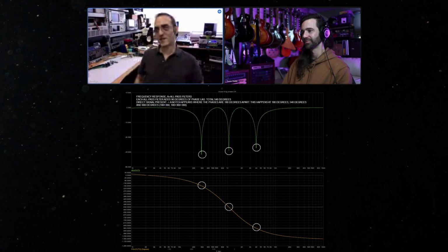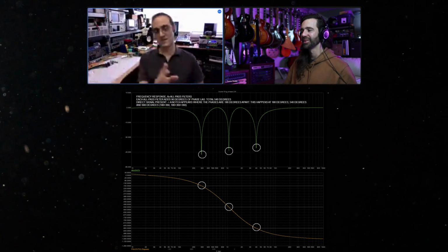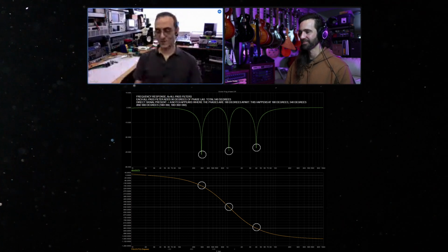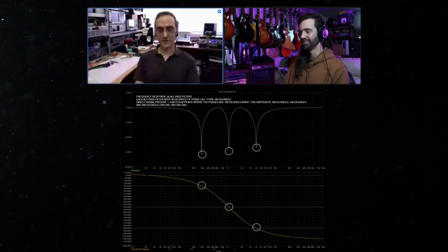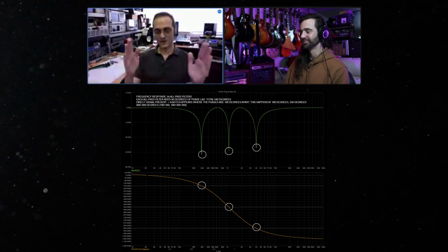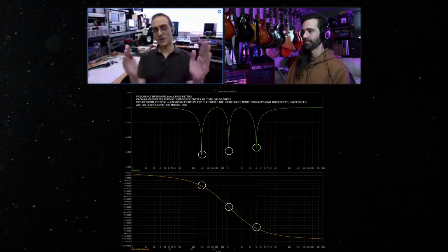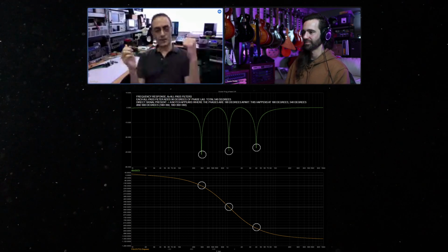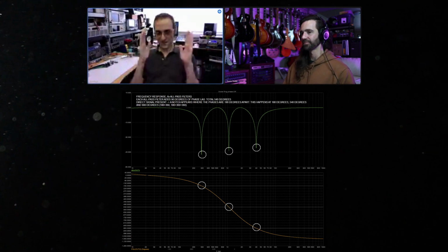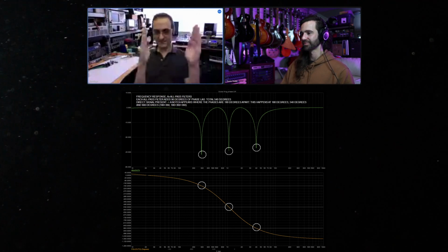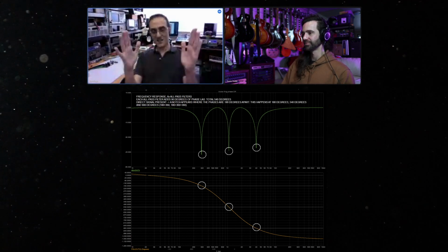I mean, in a nutshell, it's the same as a flanger, but the notches of the comb are in different places. Right. Okay. Because in the flanger, you get your signal, you delay it all the time by the same amount of delay. Your 3 milliseconds, your 7 milliseconds, whatever, is fixed. So it doesn't matter if you're playing a low E or a high 24th-fret E on the guitar, it gets delayed 7 milliseconds. Okay, right. So the whole signal is just shifted, or backwards, depending on what you look at. But anyway, the signal is delayed as a chunk altogether.